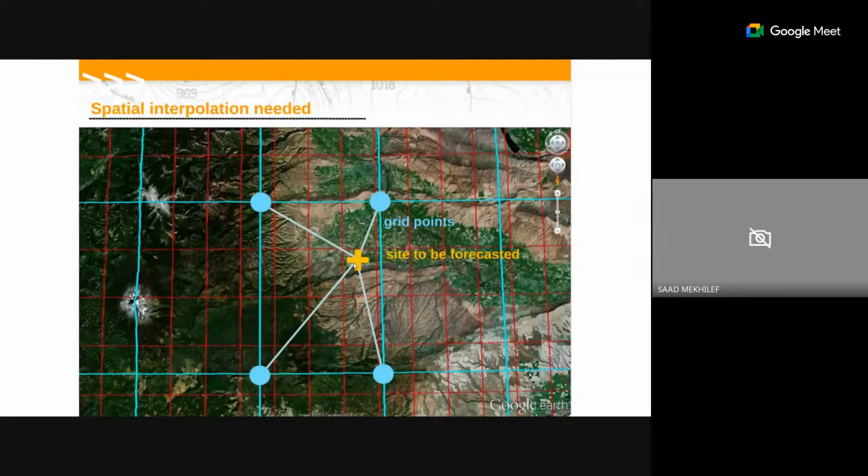But also, we may have a good site with a good wind speed, but it is very far from the load center. If it's far from the load center, it's fine. Is it very far from the grid connection point? If yes, how much does it cost to do grid extension to that location? If it is too expensive, then just forget about it, because grid extension is quite expensive. That's why we start surveying with these kinds of parameters: load centers and the grid connection. So that's very, very important.